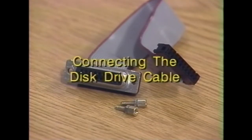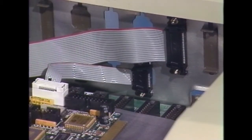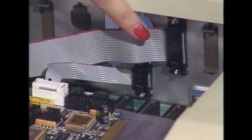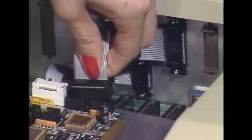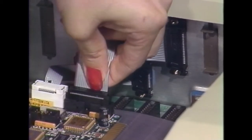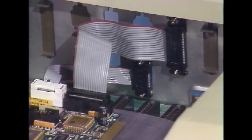Now, connect the disk drive cable. It is a 19-wire ribbon cable with a female 20-pin flat cable connector on one end and a female 19-pin connector on the other. Mount the 19-pin connector onto the backplane using the screws provided. Again, the stripe must be on the top edge of the cable. Now, attach the female 20-pin connector to the male 20-pin connector on the transporter. This connector will fit easily in one direction only.